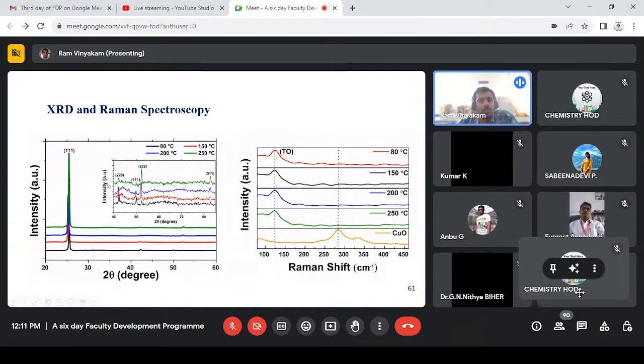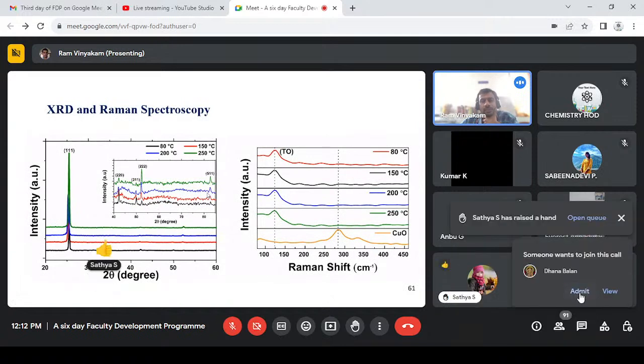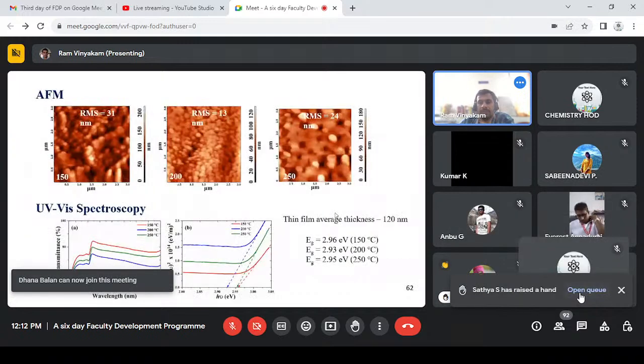And what influences here in the case of copper iodide is that we have a particular aligned growth. One plane has a faster growth rate compared to the other, as discussed for the nanorods too. Other vibrational studies were also done, and one matter is that whenever we take these halides, they easily tend to form an oxide. If there is an amorphous oxide, it cannot be detected by conventional characterization, so we used Raman spectroscopy to check whether copper oxide is present. Fortunately, we don't have any.